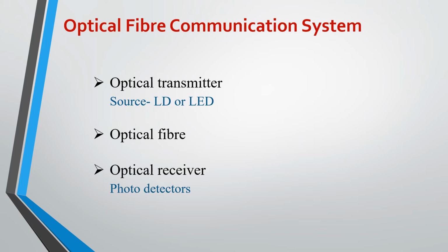These encoded optical signals are then transmitted through the cabled glass fiber. At the receiving end, a semiconductor photodiode or phototransistor receives and decodes these optical signals. For long distance transmission, repeaters are used in intermediate stages to amplify the peak signals.